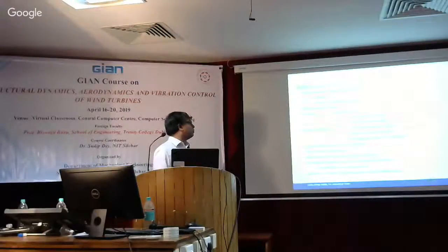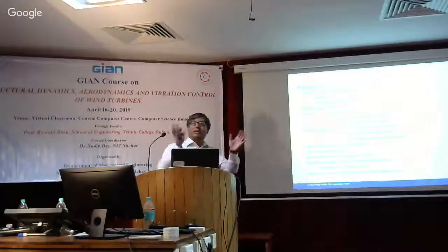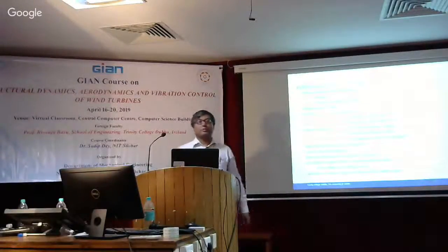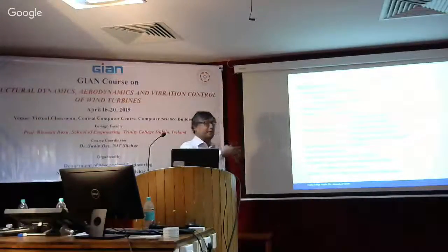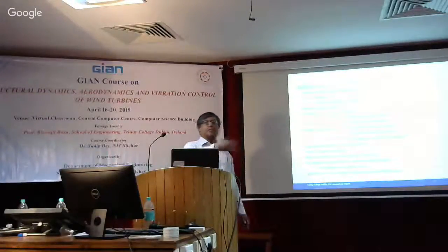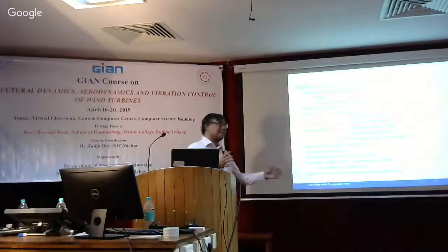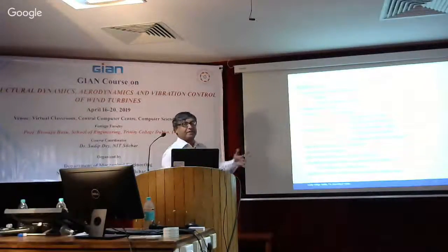So the two things also can happen. One is the pitch can act individually, or the three blades can have three different controllers, in fact. So individual pitch controller is also possible. That's a more recent one, only 2010 and 12 we started. So what we're discussing is quite recent, in the past 5, 6, 7 years, what's happening.